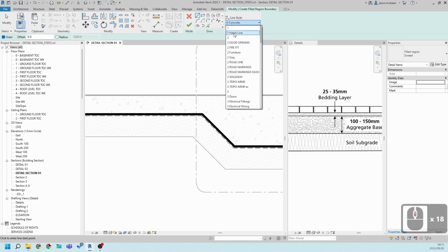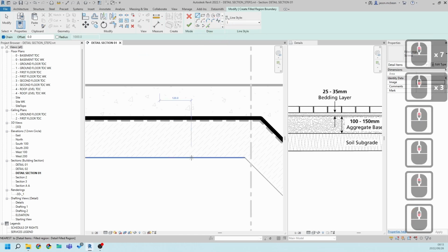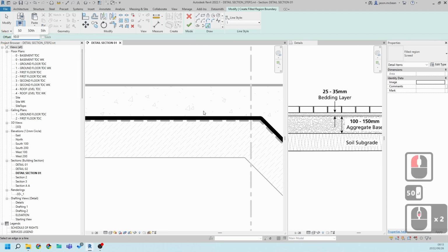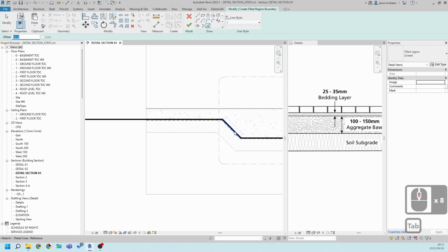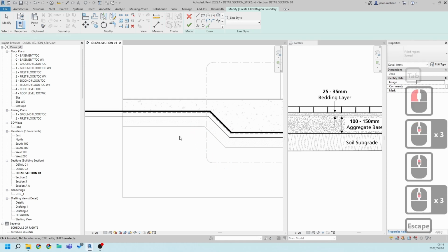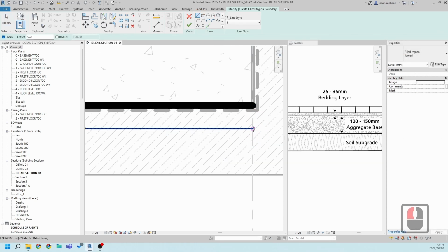I use the hatch line for this, or line 1, it doesn't matter, so I'll use line 1. Just whatever works for you. So pick this tool, and I'm simply going to say pick tool, offset 50. And if you tab on this line work, so hit this command again, pick line, tab, now you can see, perfect. So there's my sand layer. Just close the sand layer off.